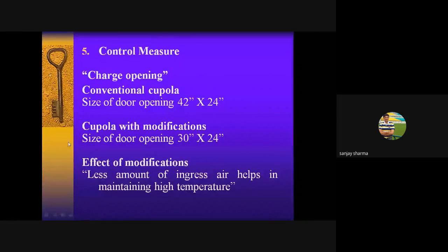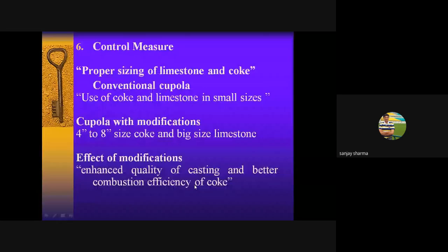Charge opening was again changed. The size of the door opening was 40 to 42 inch, and in the modification the door opening was reduced to 30 inch. The effect was that less ingress of air helps in maintaining the high temperature.